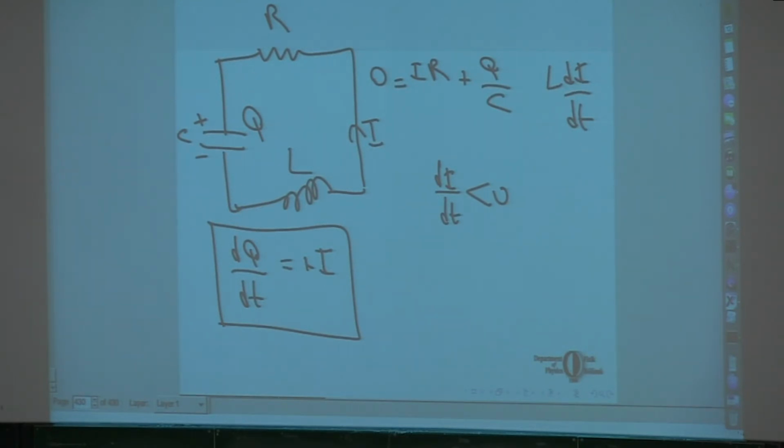If you use the analogy that this is like a battery which is pushing the current in this sense, this will be the negative terminal and this will be the positive terminal of the battery. Now, if we go from here to here, we are going to a higher potential. If we are going to a higher potential, the potential drop should be negative. But we already know that it is L di by dt, which is already a negative number. So we are just adding this negative number.